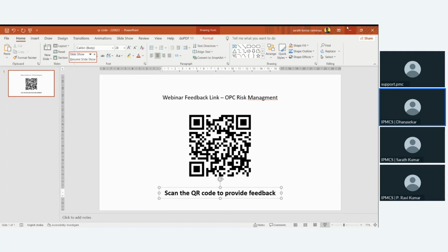Okay. Fine. So can you share something about OPC in general, irrespective of risk management? How does it analyze the schedule? Is there any schedule check facility available in OPC? Yes. Apart from risk, in OPC, normally during our schedule practice, most planners will be aware of the DCMA check, the 14-point check. That is predefined and inbuilt in OPC. So we can use that DCMA check to check the quality of our schedule. That will give the report.